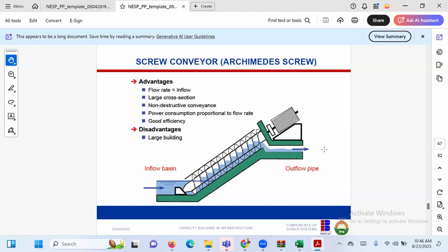Okay, and that's the first thing. You stay there for some days or for some hours while being aerated. From there, you move to the secondary. From the secondary, you remove nitrogen, you remove phosphorus, you add whatever you want to add, or you recirculate it more. From there, you move to the effluent, or you move to the denitrification or other, depending on what you want to remove from the treatment plant.